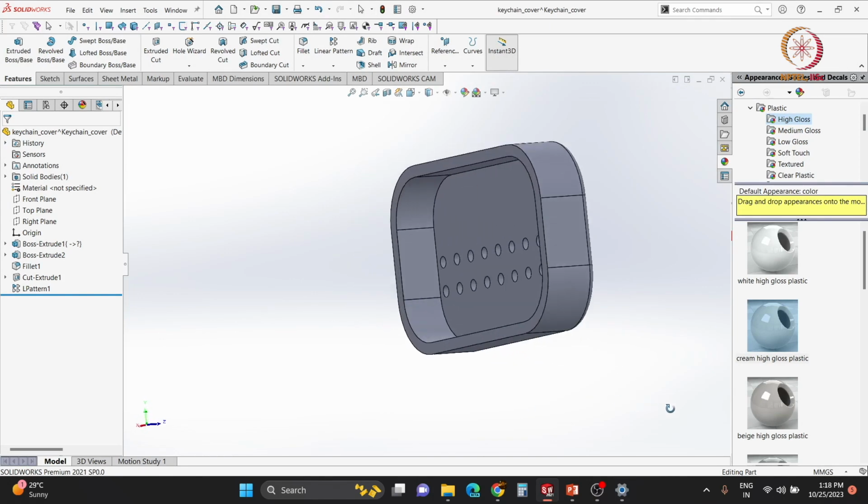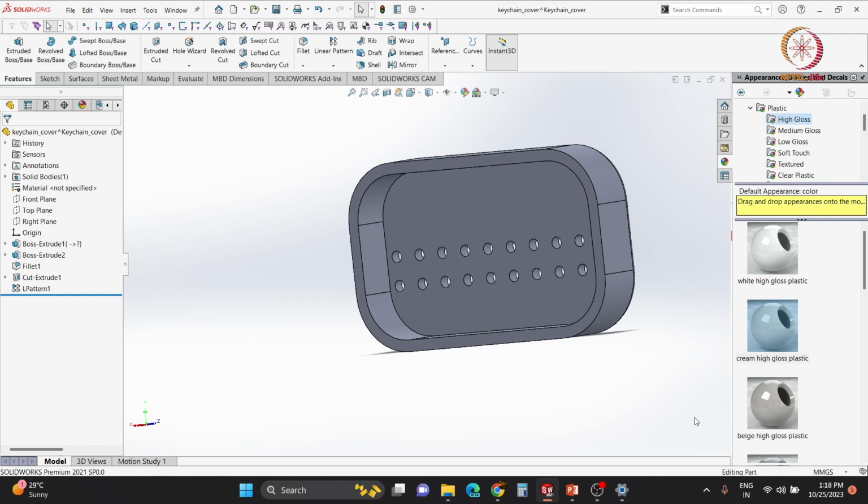Okay. So now we need to 3D print it. We have already discussed that in order to 3D print something, first we make a 3D model, either by making a model from scratch using 3D modeling software like SolidWorks, AutoCAD, even Blender or anything, then we need to convert it into a mesh file. Mostly we use the STL file format. Then we will slice it, and only then can we send that file to our 3D printer. It can be sent online, or by pen drive, or any means, depending upon which printer we are using.